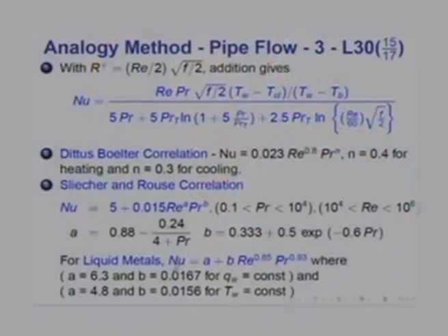The thermal boundary layer thickness now enters the transitional layer and also the inner part of the turbulent layer many times, depending on the value of Prandtl number. And in such situations, the boundary condition begins to influence events even in turbulent flow. And that is what is shown here, that the constants A and B should be modified as shown here for q wall equal to constant and T wall equal to constant. So, what it shows is again the Nusselt number for constant wall heat flux will be greater than the Nusselt number for constant wall temperature, a circumstance very similar to that found in laminar flows.